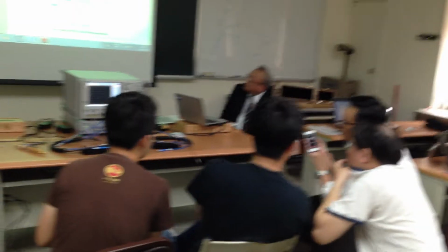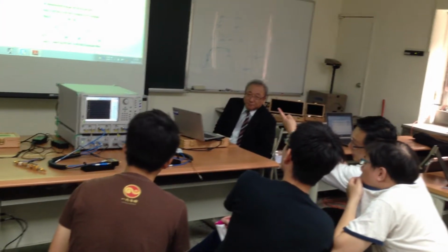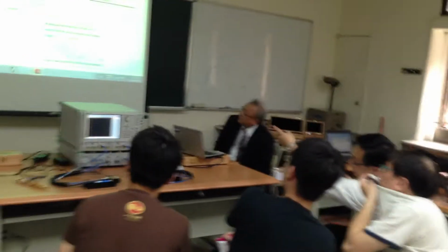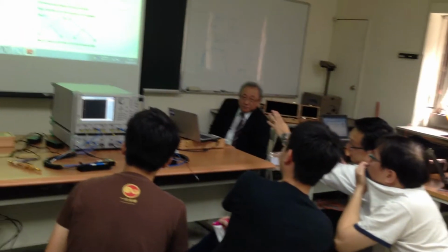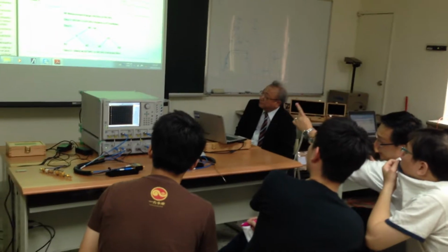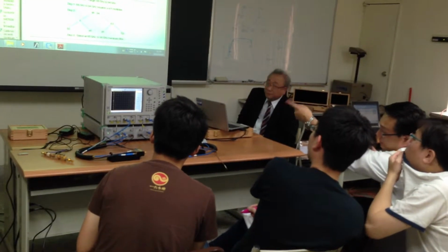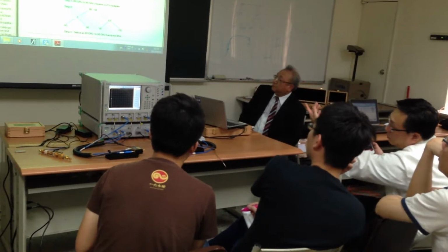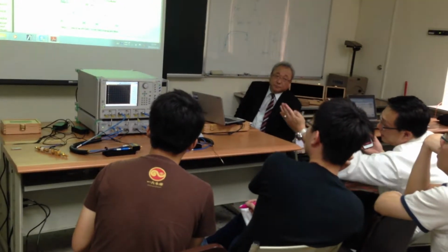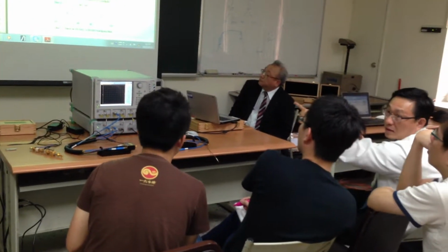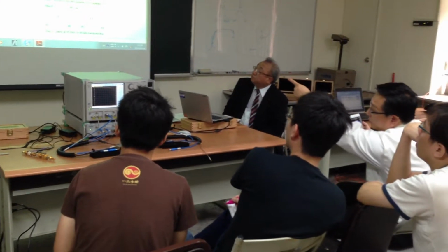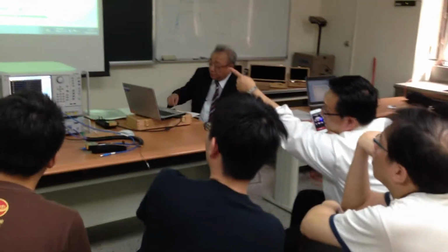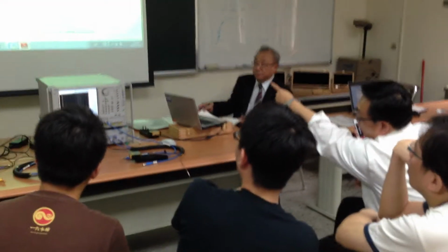So basically, Dr. John Martin mentioned, for example, the 88 gigahertz using multiplier 11, divided by 11 is 8. So the image frequency is at 80 because times 10, and times 12 is 96. So you know the image frequency is at 80 and 96 in this example. And also for your amplifier, 94 gigahertz on the top, its image is at 85 and 102.